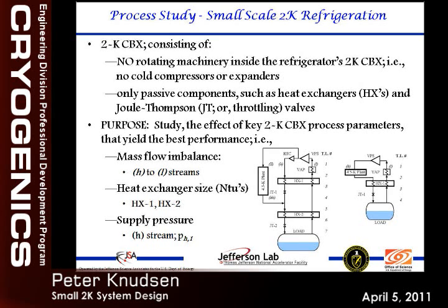I'll discuss this more in detail later, but basically, you'll see this in pictures later on. This is representing the load. So this is the 2 Kelvin nominally liquid. This represents a heat exchanger. This is the vacuum pump. This is a positive pressure compressor. This represents the 4K liquefier, which consists of the cold box and a compressor.